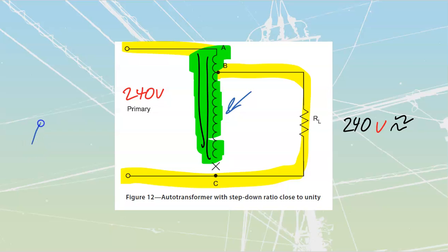The instant that we start crossing with our sine wave into there, we're going to almost instantly drive this thing into magnetic saturation. Then it's going to stay in magnetic saturation all the way until we get to about here, and then it's going to drop out of magnetic saturation, just because there's no counter EMF being developed by this winding inside of here to counter that. What happens is when we get this really, really rapid drop over here, you should remember this formula: E is equal to negative L delta I over delta T.